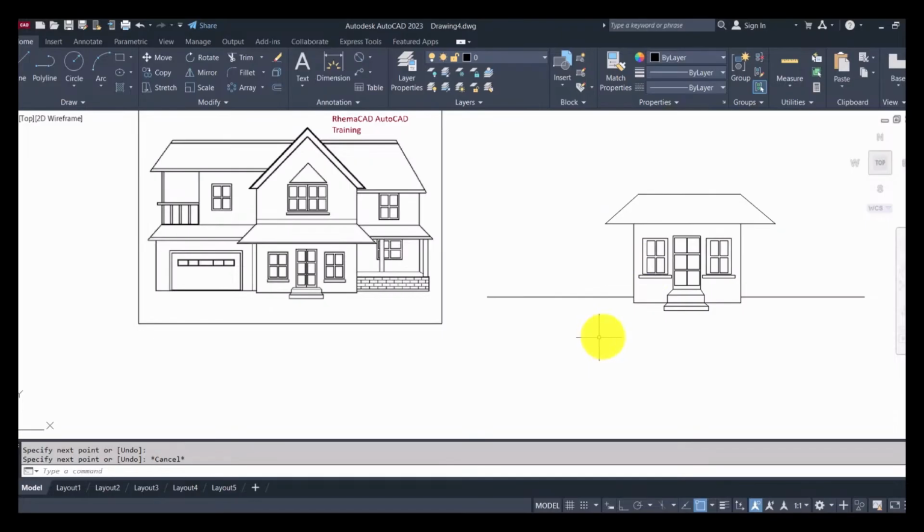So I'm going to continue with the drawing. So I'm going to move to this side of the drawing and continue. I need a straight line. Okay, now I told you when you are working, always make sure that you turn off your object snap when you don't need it. Sometimes it can make you make mistakes. So if you don't need it, always put it off.